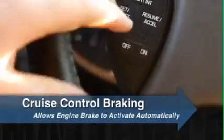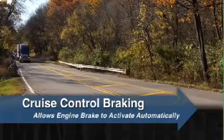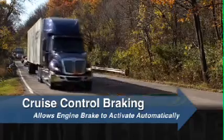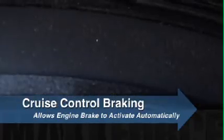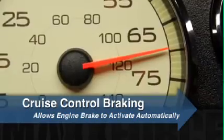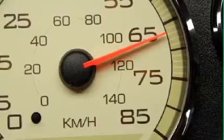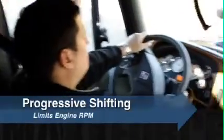An optional feature with cruise control allows the MaxForce engine compression brake to activate automatically when cruise control is engaged. The brake activation increases as vehicle speed increases above the cruise set speed until it reaches a maximum value of 100%.